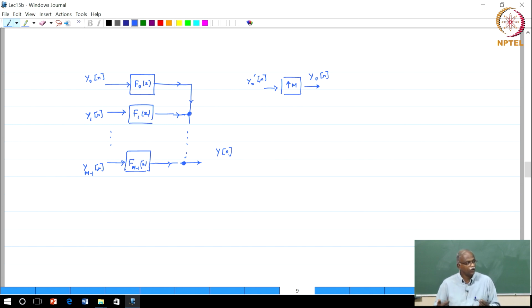Delays, either a constant or different delays, basically the polyphase notation, the polyphase structure comes into play. So this is actually quite a versatile structure. Don't think of it purely in terms of delays or filters; it could be just simple delays, in which case it's just a multiplexer structure. Regardless, this is called a synthesis filter bank, like the previous one was called the analysis. This is called the synthesis. You are combining signals into a single signal. Synthesis filter bank. These filters, by the way, are called the synthesis filters.